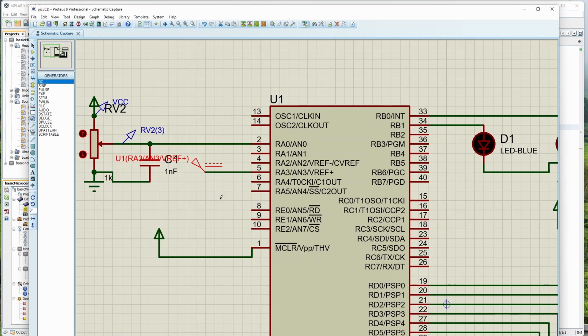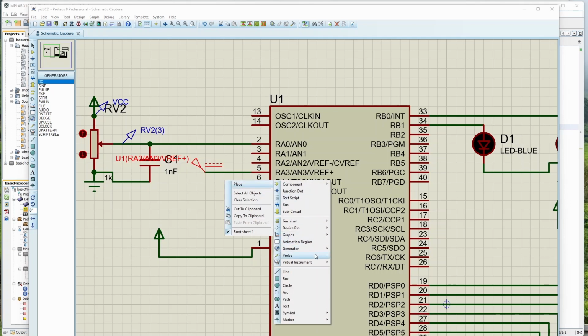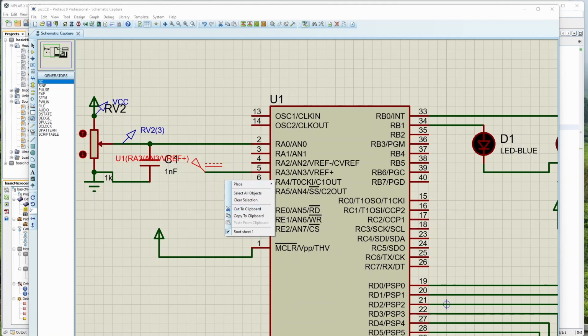If you try to capture a 0 to 1 volt variation in a 0 to 5 volt range, your resolution becomes 1/5, because you are only using a very narrow portion of your capability. In that case, you can use a V reference closer to 1 volt, like 1.25, or some voltage reference ICs you will get. I'm going to use 2.5. Let me put a probe also.